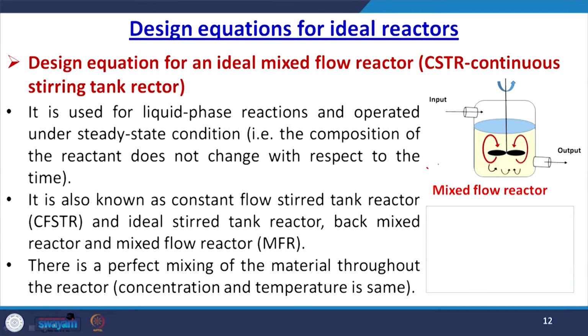Now let us have a look at the various design equations for ideal reactors. The design equation for any ideal mixed flow reactor, or CSTR, continuous stirred tank reactor, is used for liquid phase reactions and operated under steady state conditions, and this condition prevails that the composition of the reactant does not change with respect to time.